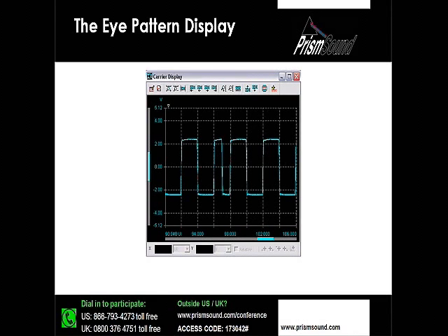And this is another great tool that the D-Scope affords you, the ability to look right into the data stream as if you had such a tool. I might also point out that even if you have a tool like a high bandwidth storage scope, there are triggering issues that you have to take into consideration. If you don't trigger on the signal properly, you can actually get totally wrong results, or if nothing else, inaccurate results of the jitter that you're measuring.